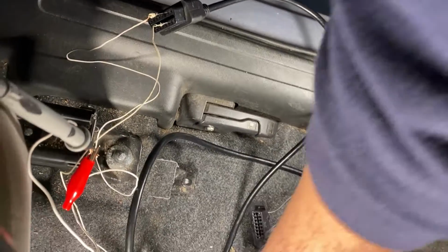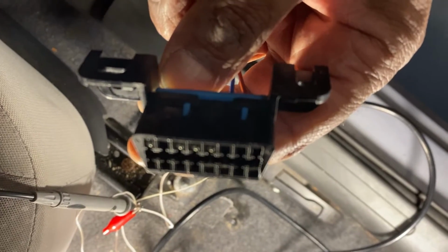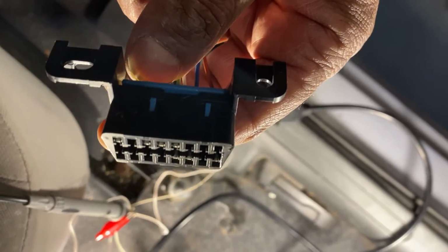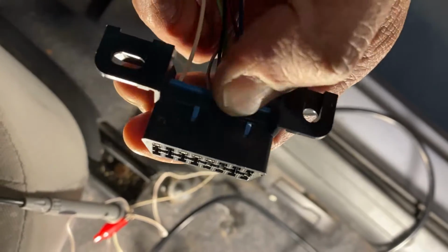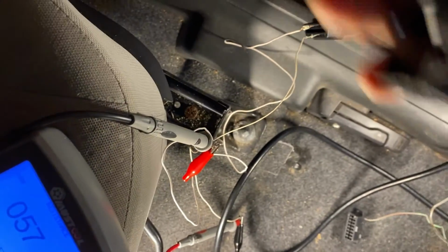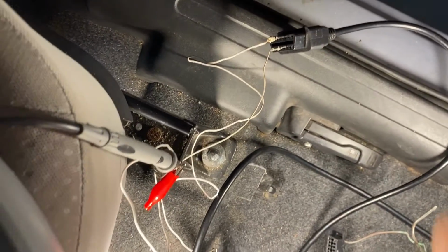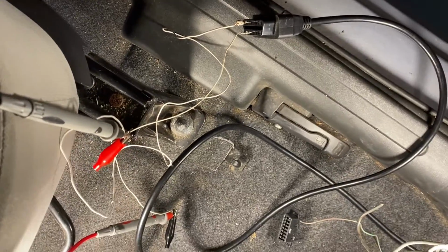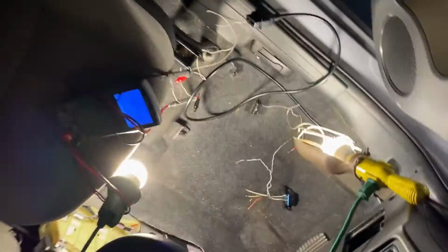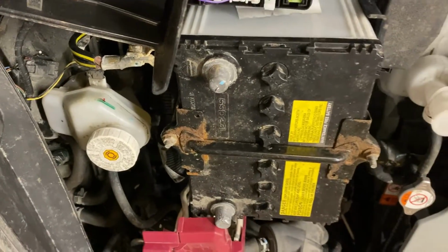And it's good also to have a breakout box. You can make it yourself. It's very cheap, or you can buy it, or if you have spare time, just get this wire connected to an extra terminal. You're going to connect your multimeter. Okay, so before you do this test, you need to disconnect the battery, as I show you right now. So we disconnect the battery, okay?